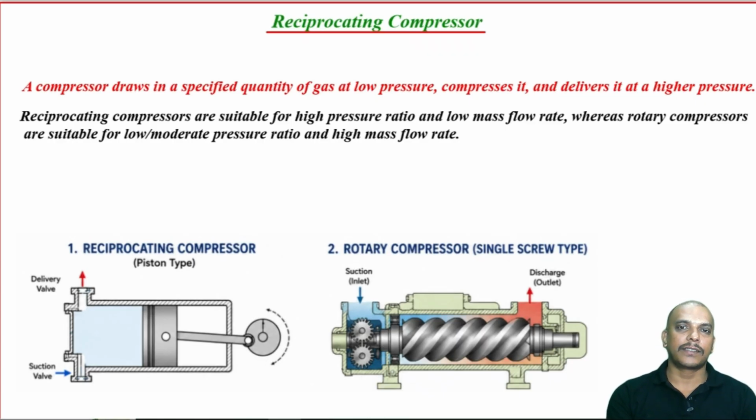In this video, let us learn about reciprocating compressor and we will also derive work required for a single stage compressor without clearance volume. Now, what is a reciprocating compressor or what is a compressor? A compressor is a device which draws specific quantity of gas at lower pressure, compresses it and delivers it at a higher pressure, correct? So, there can be a compressor based on its action.